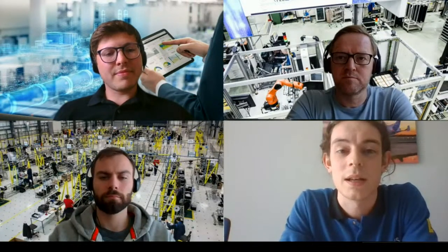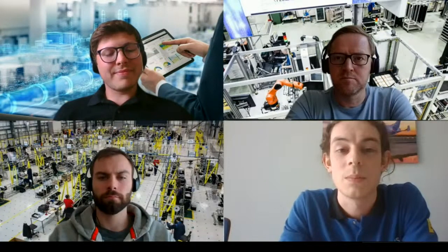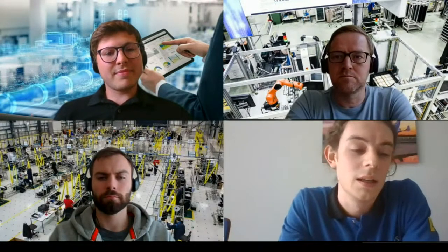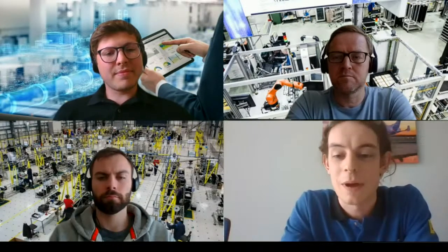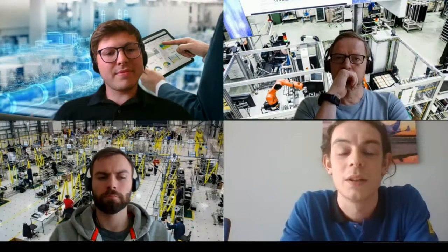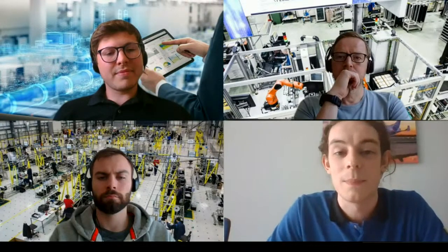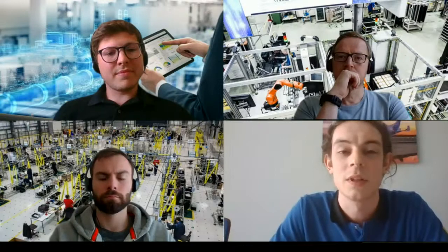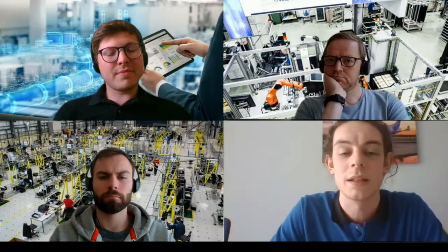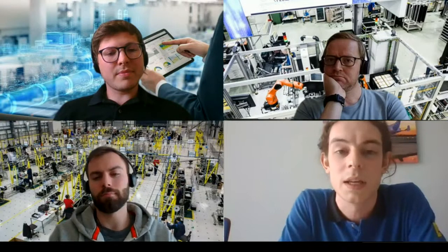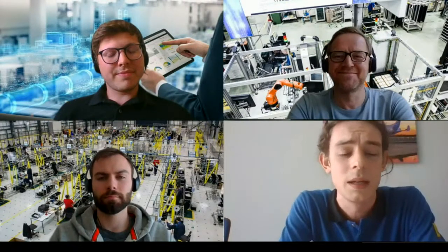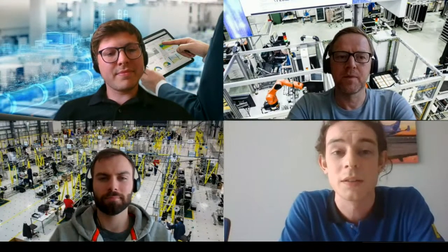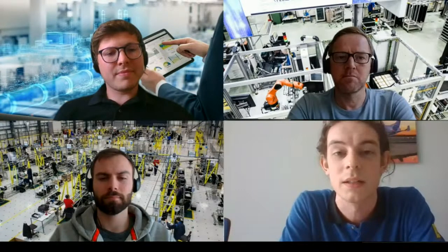It's keeping to best practice and making sure that our products within Congleton, Siemens, are built efficiently and the quality is what we need. For the ventilator challenge, we needed to create timings from our bedrooms, our kitchens, all of this sort of stuff. All we had was a video from Penlon of an operator building this ventilator, and we had to break it up into little chunks and take timings from that video. Then we could input that data into what we call discrete simulation software, called Plant Simulation. It's another Siemens software. From that simulation, we could determine how many ventilators we could make in a week or in a day, and how many operators we might need. You heard Matt earlier say that we need 500 operators, and that number was generated from the model.